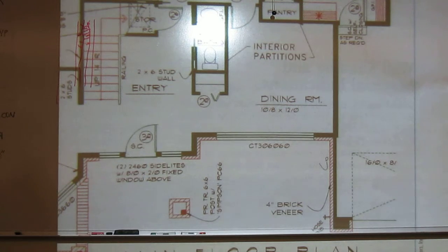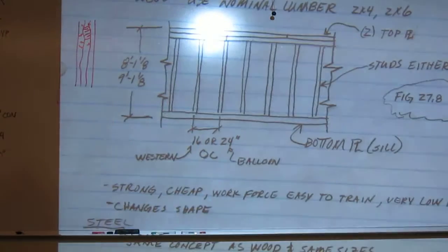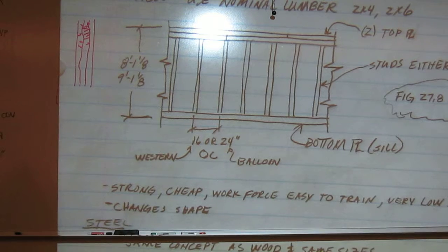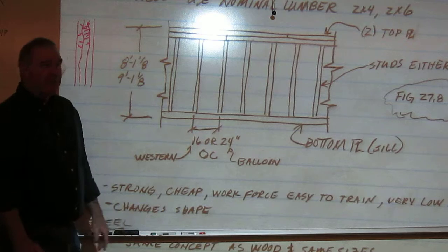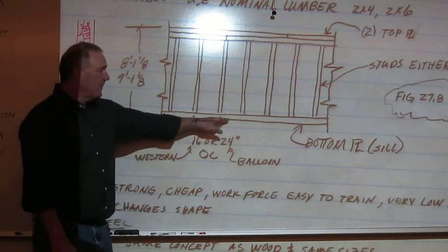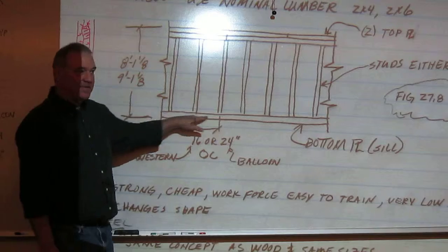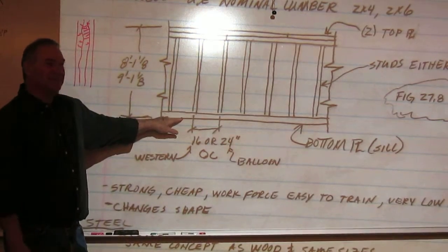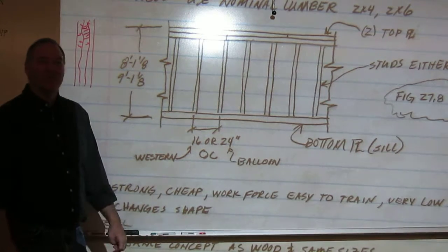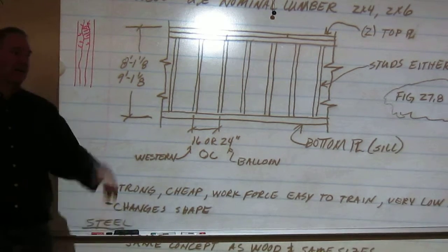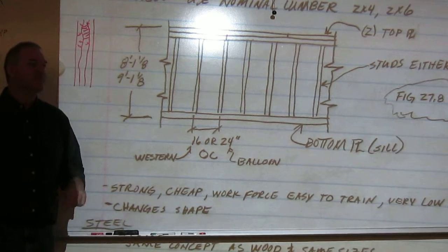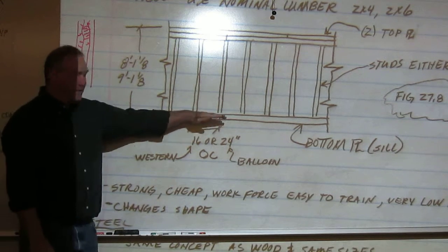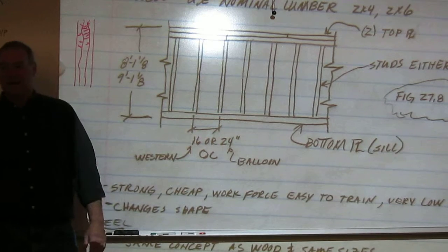So when we do this, here's a typical wall that's done in our industry. You have 3 real components here. You have what we call a sole plate. That's its bottom piece. It's also called a bottom plate. I think the technical word for it is a sole plate. That kind of means the bottom, right? The sole of your shoe. So this is your bottom piece. It's laid in a horizontal fashion.